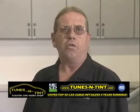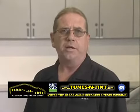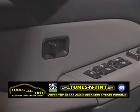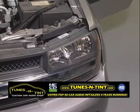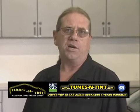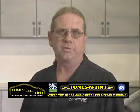Now that you've followed all the detailed instructions in your owner's guide and installed your new directed system, let's test some of the typical features. Number one, the keyless entry system. Pressing the lock button with keyless entry functionality locks your doors. Pressing the unlock button will unlock your doors. You will also notice light flash confirmation: 1 flash for lock, 2 flashes for unlock. Some DIY systems also provide horn honk confirmation in addition to the parking lights.